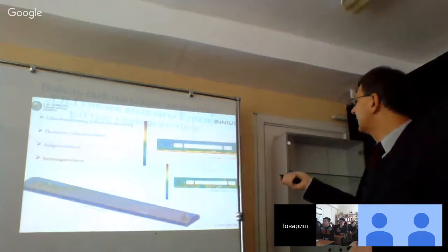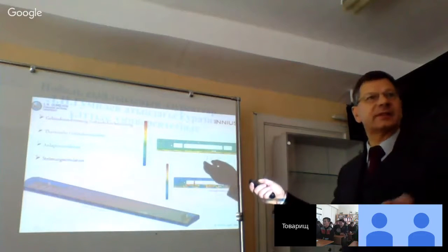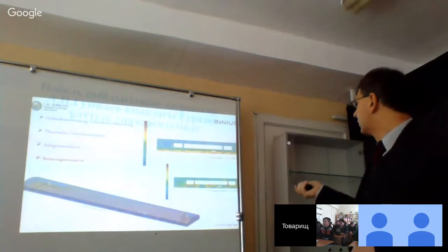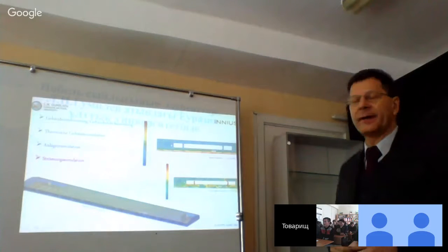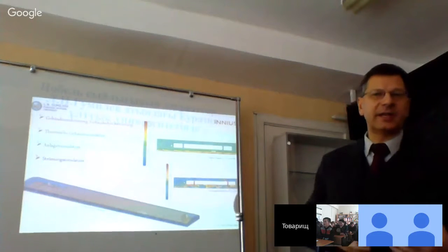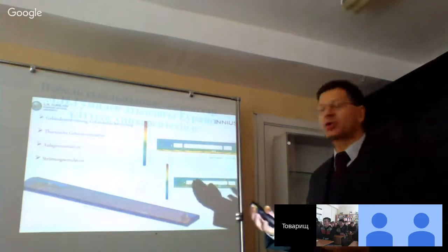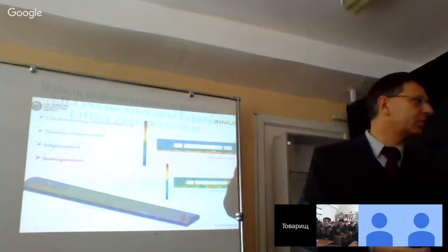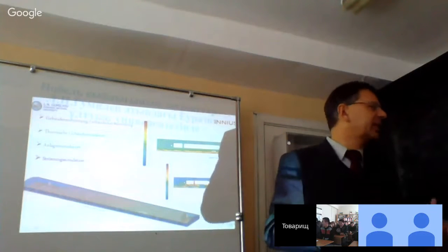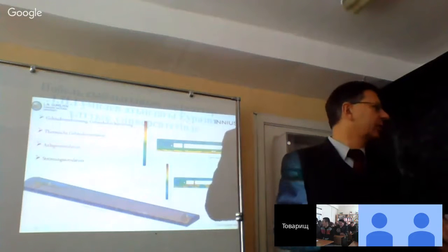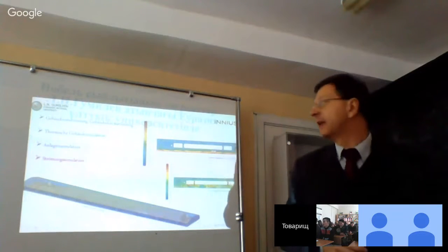Over the whole terminal, you see the higher temperature on the lower side, where the sun comes into the room. And you can estimate the air velocity, and depending on the air velocity, the temperature, the turbulence, the surface temperature, you can predict the thermal comfort which you can get in the room itself.